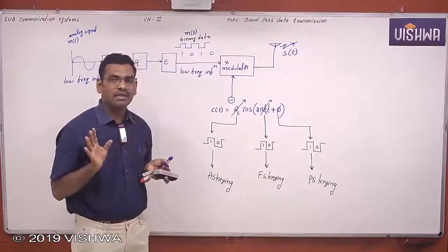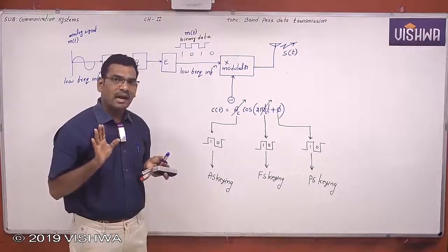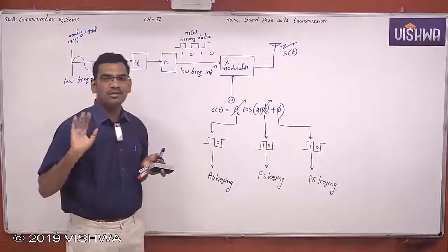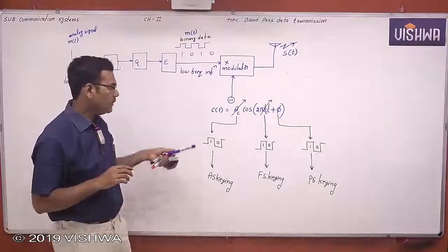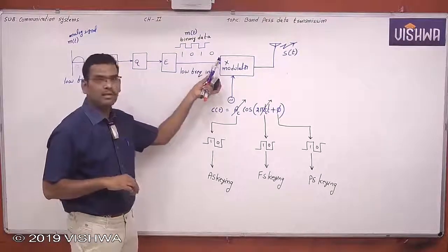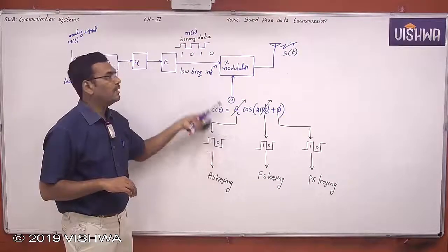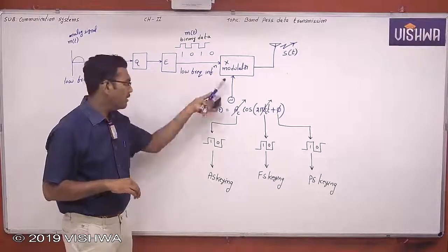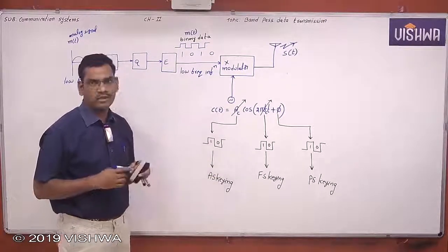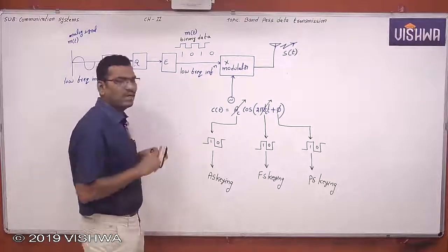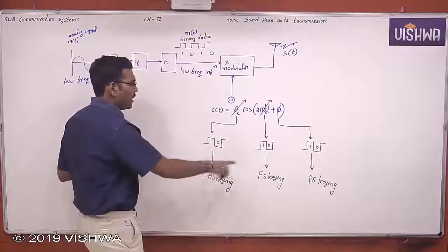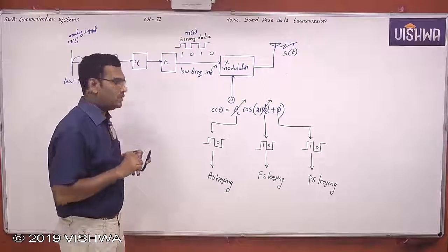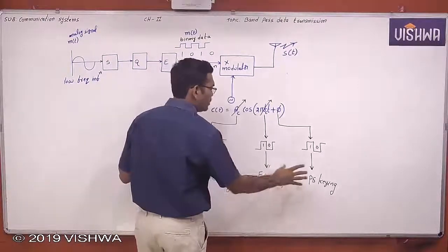Those techniques are converting an analog signal to a sequence of ones and zeros in a different process. Now those ones and zeros alone cannot be transmitted without a carrier. Those ones and zeros can be transmitted from one point to another point with the help of a carrier. Then this is the modulation process. So this is the actual modulation in a digital communication system. So we also call this the digital modulation technique.